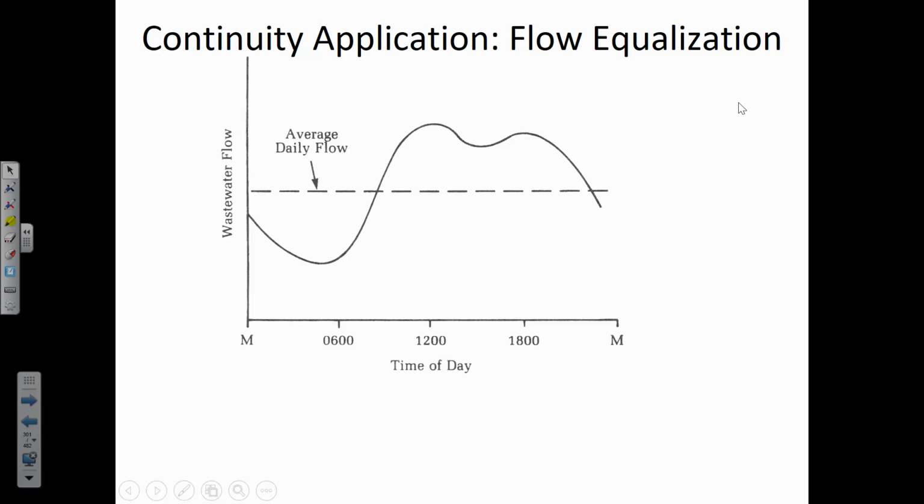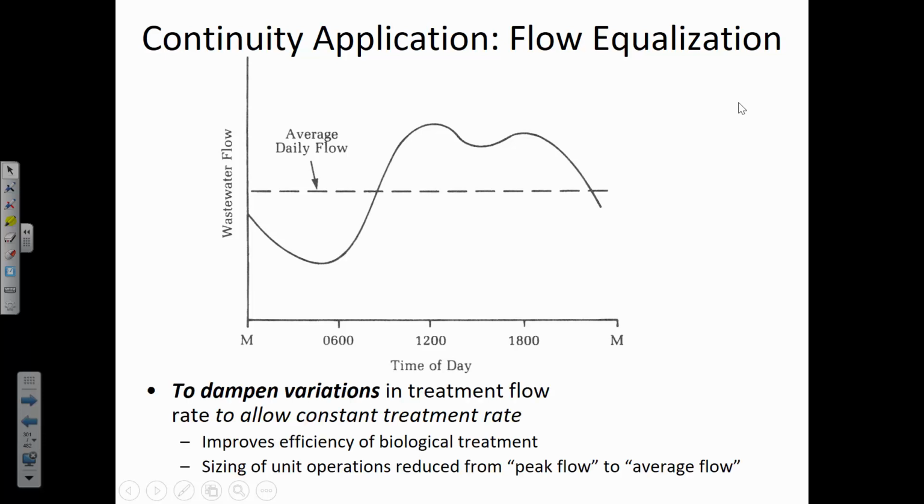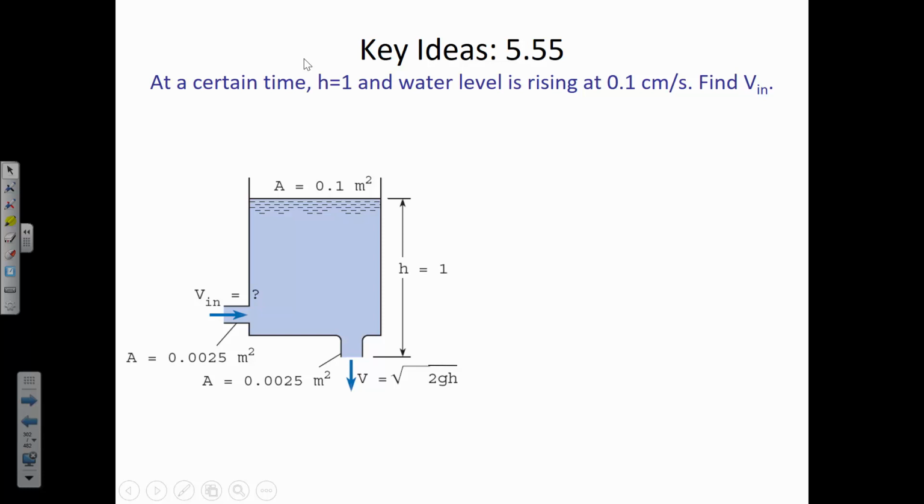And that particular wastewater treatment plant is pretty close to a really expensive neighborhood in Dubai. So people don't pay millions of dollars for a house only to have the smell of a wastewater treatment plant. So you have to be a little bit careful about some of these storage basins, but the main idea here is that we can use the idea of accumulation in combination with a treatment process that's microbial, because the bacteria don't respond as quickly as a chemical reaction or a physical reaction would.